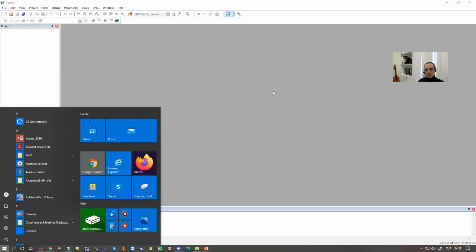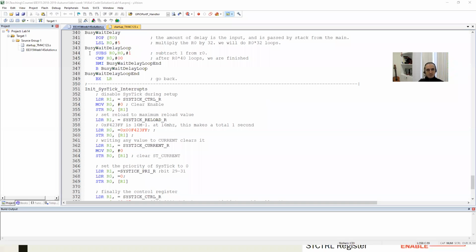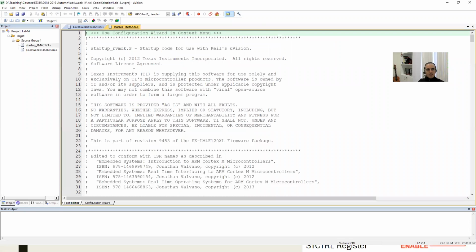Remember, when we were talking about the priorities, so you can see my screen now with the code. We said that every interrupt is listed in the so-called interrupt vector table with a specific order, which is designated in the data sheet. So if this timer can also create an interrupt, it is an interrupt source, then it should be somewhere in the interrupt vector table.